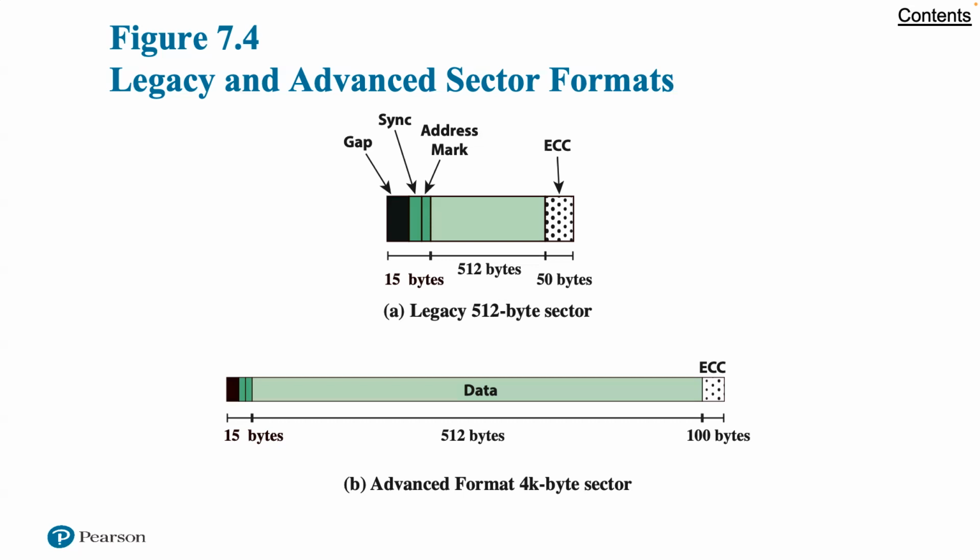The overhead consists of 65 bytes, yielding a format efficiency of 512 over 512 plus 65, so it gives about an 88% efficiency. Second, bit density on disk drives has increased substantially so that each sector consumes less physical space. Accordingly, a media defect or other error source can damage a higher percentage of the total payload, requiring more error correcting strength.